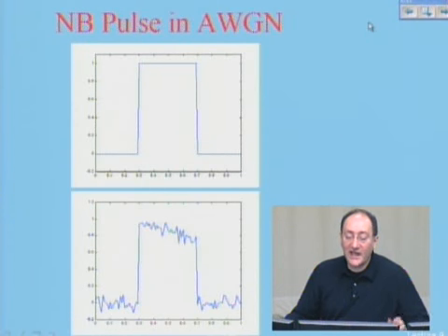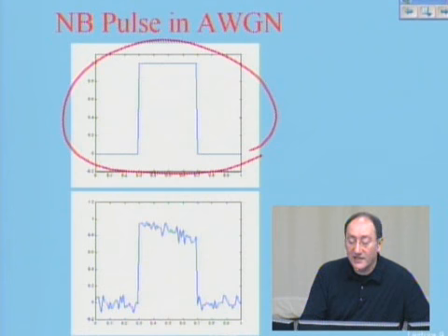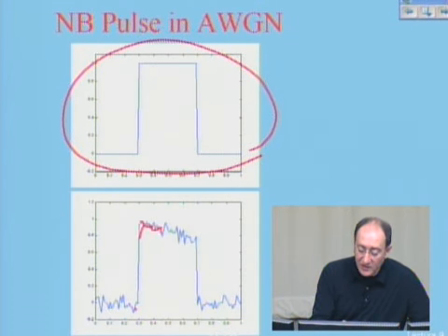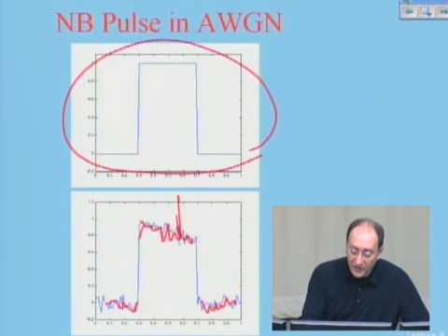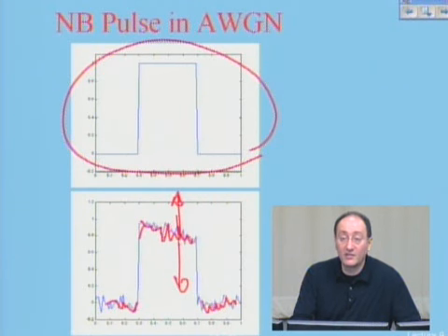So if I have narrowband communication and I want to send a pulse, the simplest pulse ever is a square pulse. If I send this square pulse, at the receiver I receive that square pulse plus this noise. This is additive noise. And then the total amplitude always goes up and down due to the effect of fading. So it goes up, it comes down.